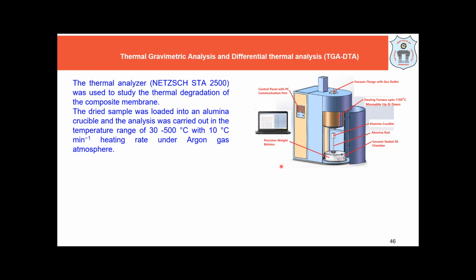Depending upon the material, you can change the temperature. So what you will know is how the weight is decreasing. For example, up to 100 degrees, you can say that the decrease in weight is because of moisture content. Then up to 200, less volatile, meaning highly volatile material. After that, low volatile material, right? So like that, the composition can be determined using this TGA, which in some other course you'll learn in detail about also.